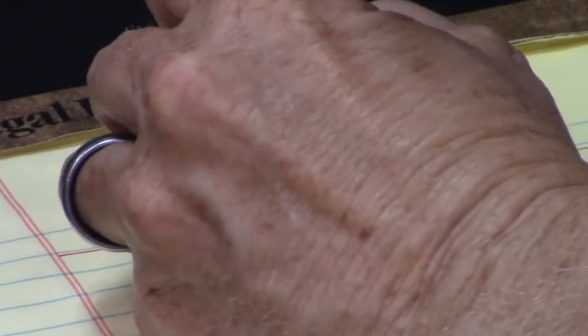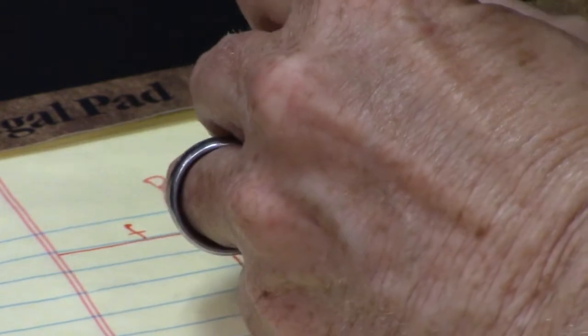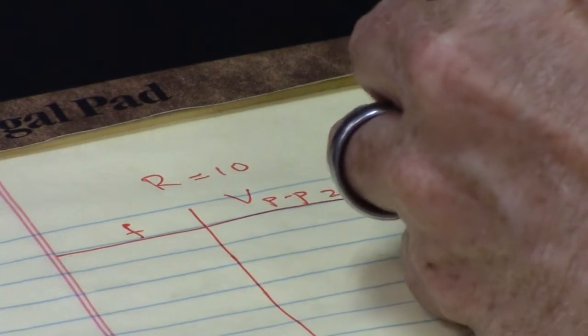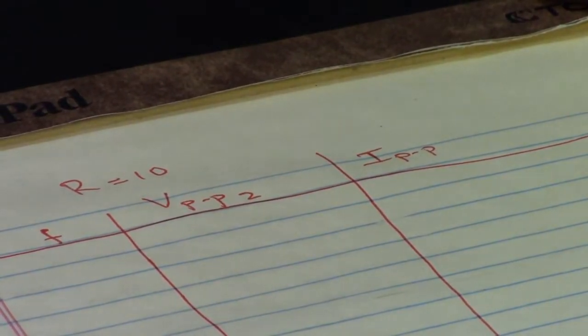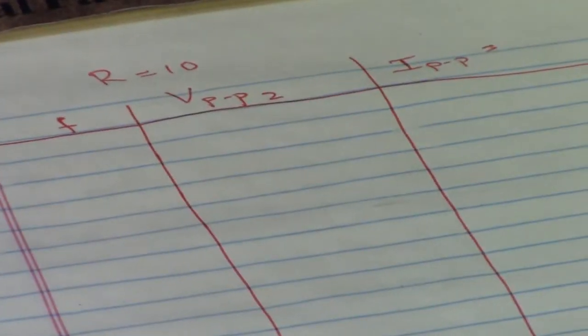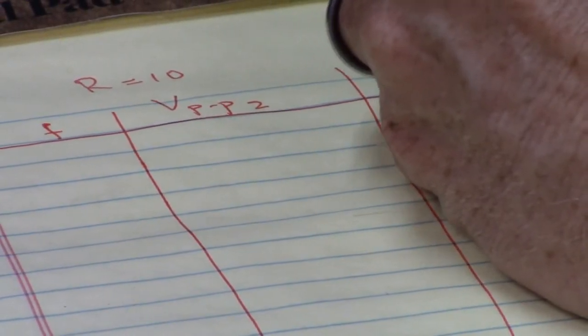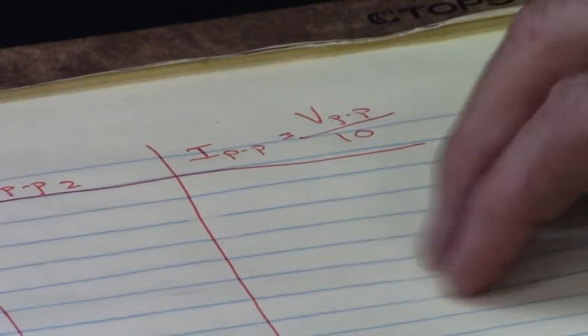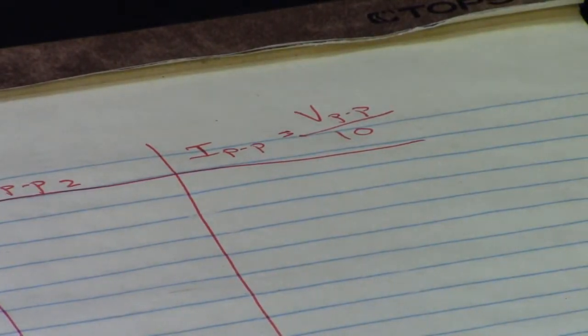And then I am going to measure the peak to peak voltage on channel 2. And so then I'm going to get, with a calculation, and that's probably what I'll leave to you, you can just divide by 10 and get the current, although I will write it as a little formula, peak to peak divided by 10, so you can kind of set up in graphical analysis this column. Okay, and so in terms of units, this is going to be hertz, this is going to be measured in volts, and so this will be measured in ohms.